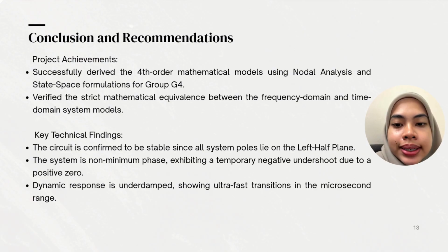First, the circuit is confirmed to be stable since all system poles lie on the left half plane. Second, the system is non-minimum phase, exhibiting a temporary negative undershoot due to the positive zero. Last one, the dynamic response is underdamped, showing ultra-fast transition in the microsecond range.